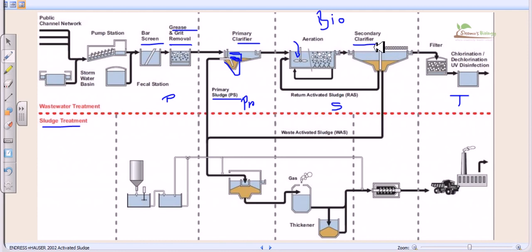In the secondary clarifier, we put this water from the aeration tank or the anaerobic treatment plant, and as a result of bacterial enzymatic action, all those small nutrients start to coagulate with each other, and they are going to settle, and form a layer at the bottom of this secondary clarifier as the sludge, and this is called the secondary sludge. And we can also drag this sludge for treatment with the help of the sludge treatment process.